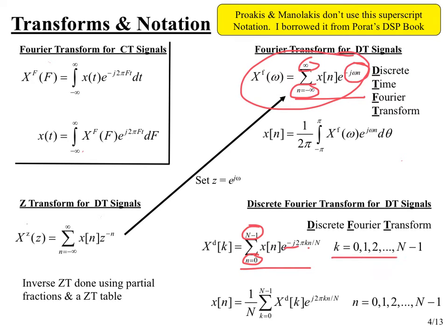And so as we let k go over these values, we are getting just a certain discrete set of frequencies, and so that's what the discrete Fourier transform is. And once we have it, which we're using a superscript lowercase d to indicate, we can do a summation to get back our original signal. So a lot of stuff on this slide, but stuff that you've probably seen before, with just a few wrinkles here, with perhaps some new notation.